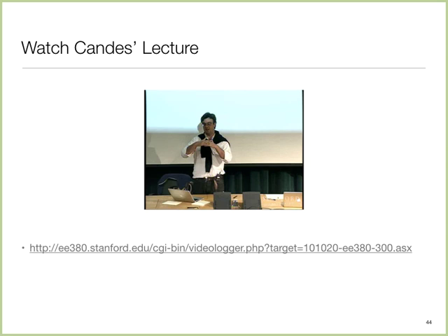Finally, one nice thing about compressive sampling, as opposed to sampling fully and then compressing as we normally do, where we capture the image and then do a JPEG compression in the camera, is that the heavy burden is all on the receive side. The sending side is basically doing this randomized sampling, which is super efficient, as you might imagine. The receive side is doing this optimization problem, whereas things like JPEG compression are designed to be more symmetric, where both sides pick up a somewhat equal burden. So lots of nice characteristics.